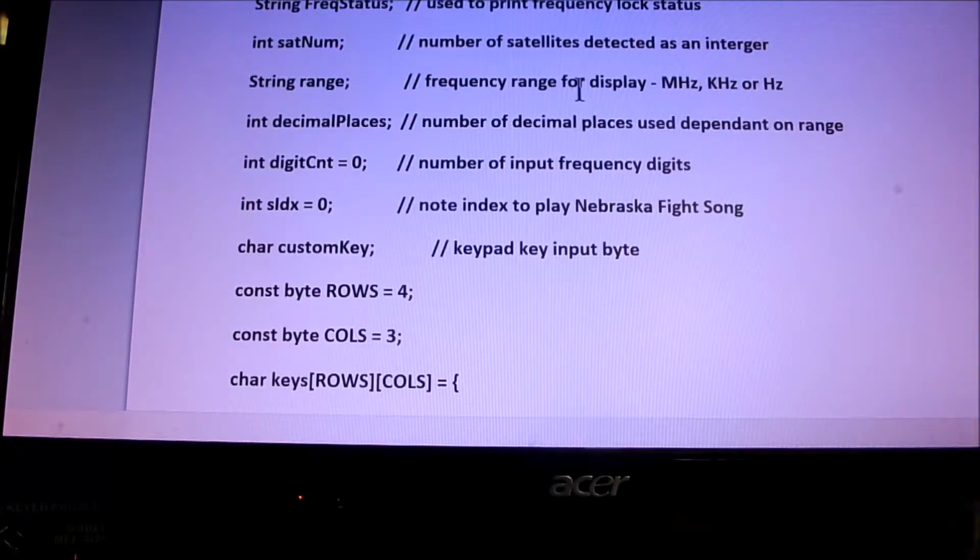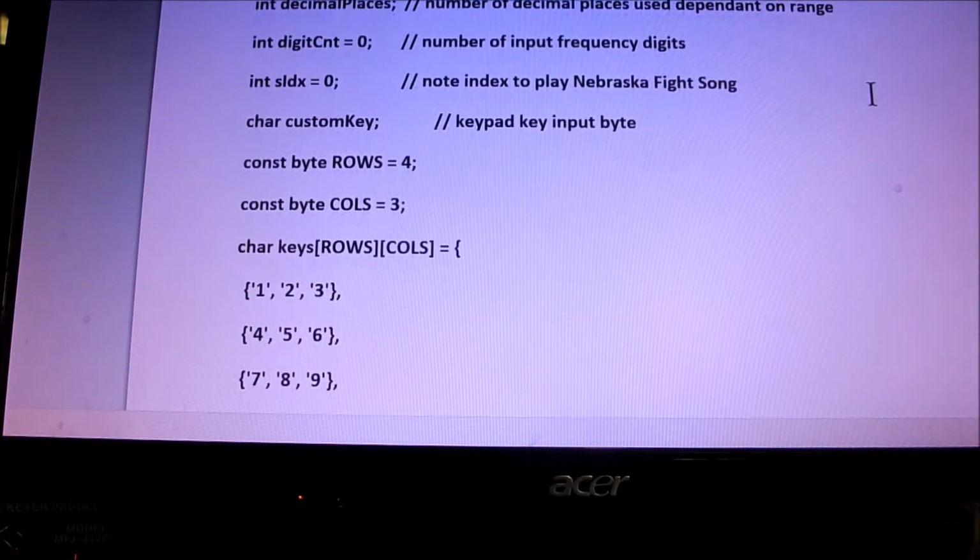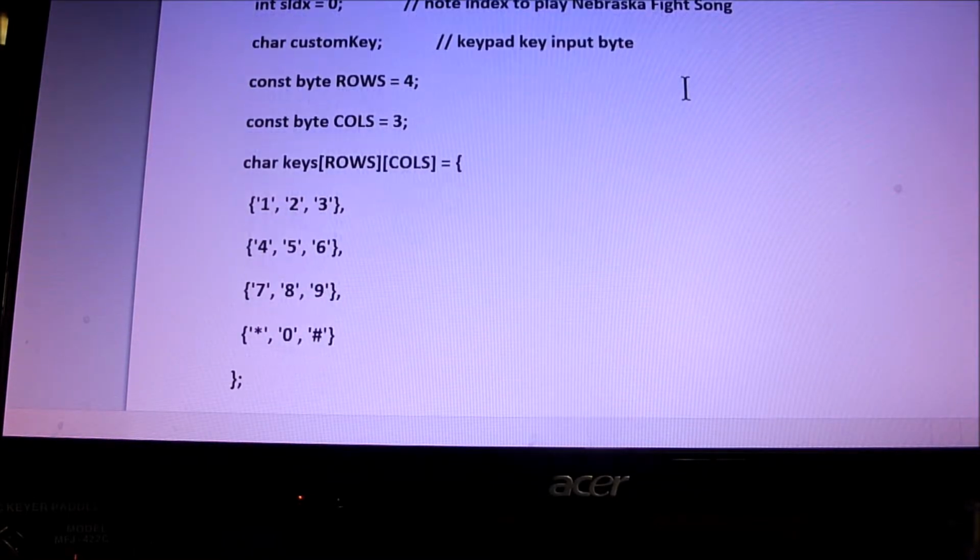here's part of the routine Jerry did to display the frequency, megahertz, kilohertz, or hertz. The original version didn't do that. Jerry's second version did, and that's a nice change. Just like with his system, when you enter the frequency, you have to do it in hertz. So if it's 5 megahertz that you want to enter, it's 5,000,000, 5 million. That's just the way it is for now. That could be changed, but what the heck, it's good enough.